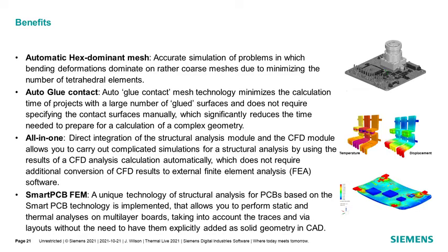Lastly, let's look at the smart PCB finite element method. It's a unique technology based on this material map nodal network to define the mesh, where you don't have to resolve the copper explicitly, but the material map itself is defining where to place the nodes, because it's doing that for the thermal side as well. So it can leverage that definition to create a very robust finite element mesh using the triangular prisms.